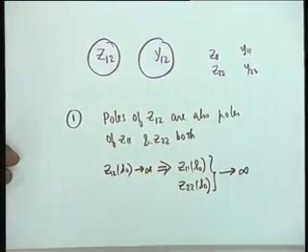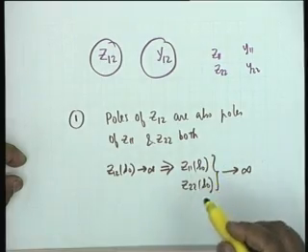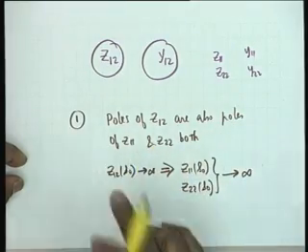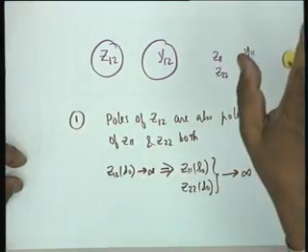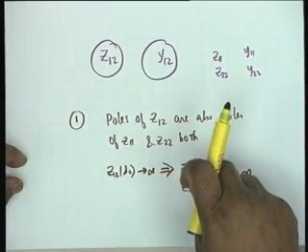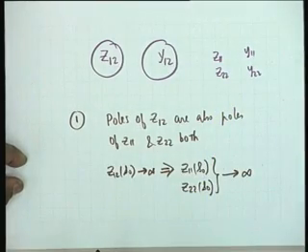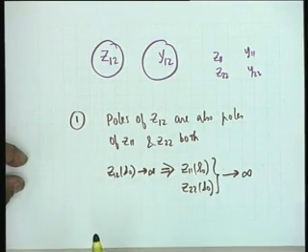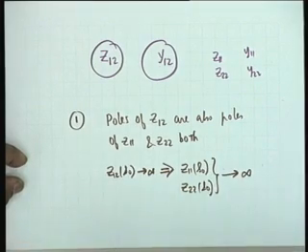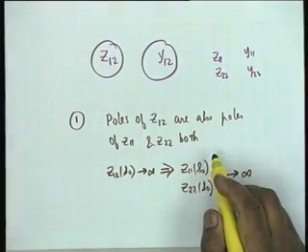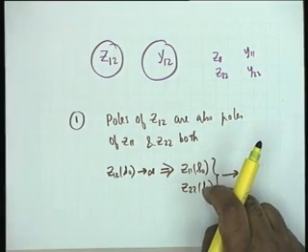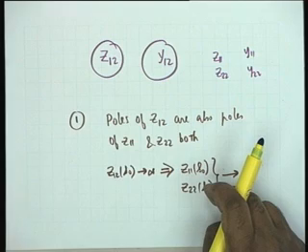That is what I was saying, that z11 poles and z22 poles can be independent of each other. They can also be independent of z12. But z12 cannot have a pole which is not shared by both z11 and z22. Agree? The forward statement is correct, the reverse statement is not necessarily true. In other words, it is possible for z11 to have a pole which is not shared by either z12 or z22. Similarly, z22 can have a pole which is not shared by z11 or z12.